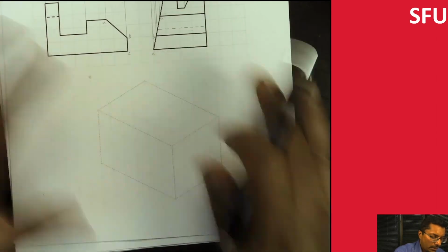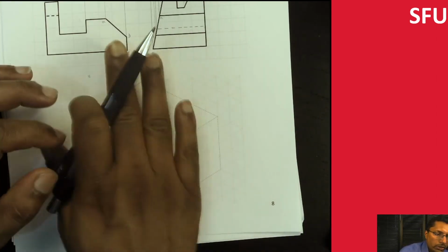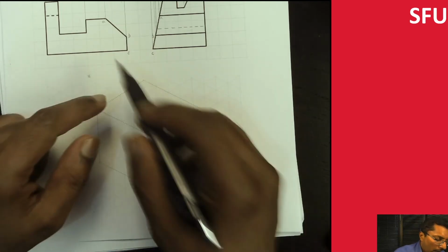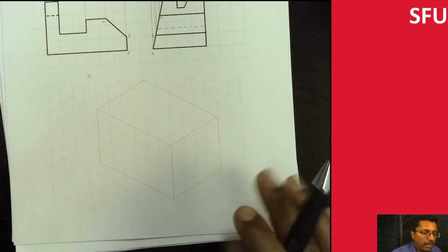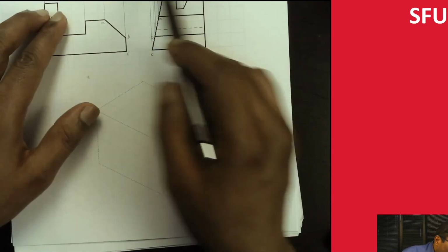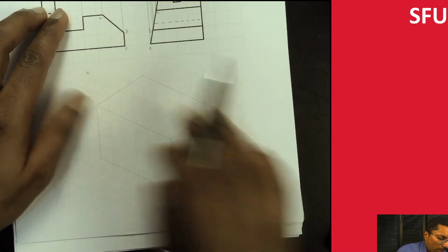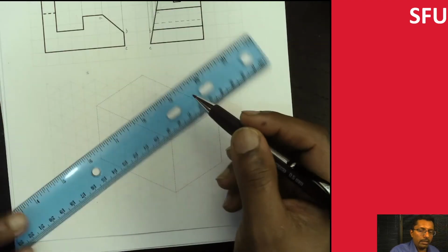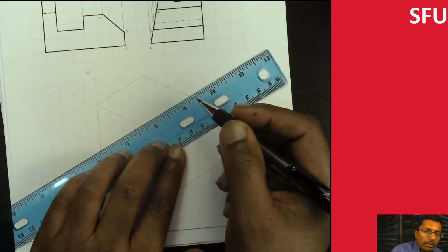Again, we are mainly concerned about creating the objects, so we're not actually going to show the hidden views. We're going to focus on the top, the right, and the front plane. As long as the lines and points are aligned, it's very easy to make them. If you look at this line, this guy here and this one, that basically means that these are exactly on the top plane. So we can create those right in a straightforward manner.